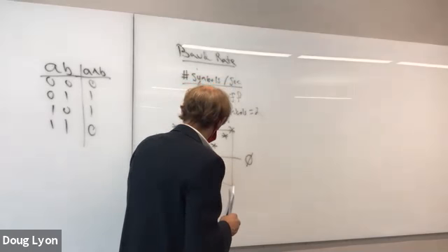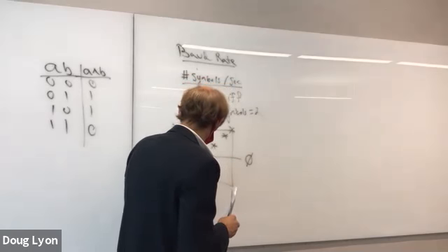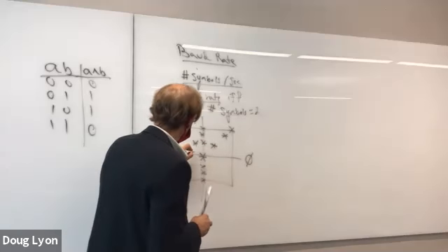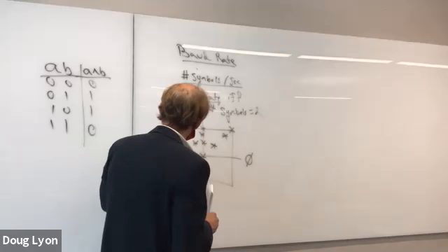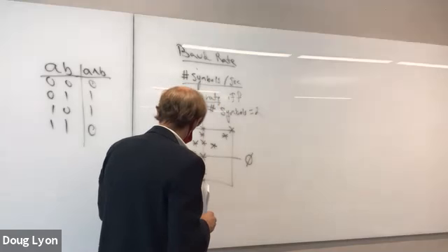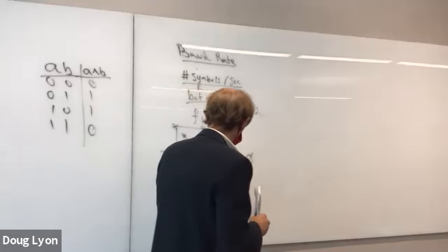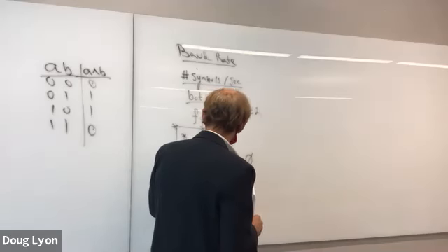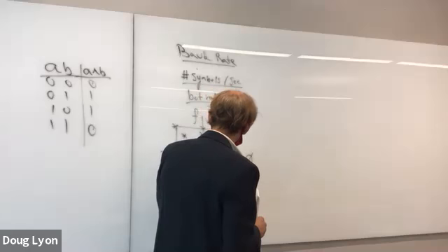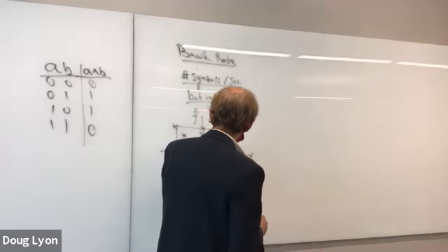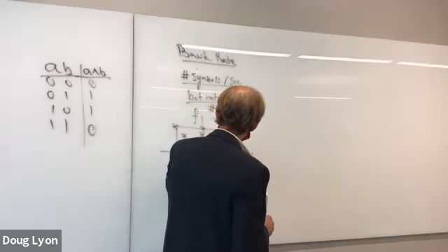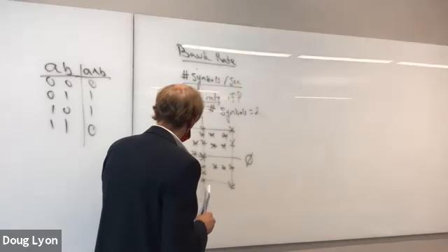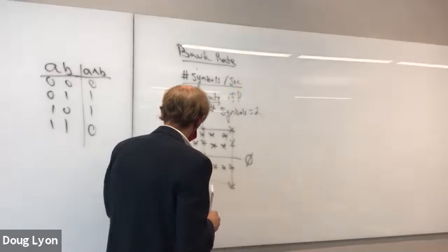And your maximum a posteriori receiver, also known as the MAP receiver, has a series of filters, which is able to determine when these symbols are being sent. And you can imagine it's just like a touch-tone phone where you send different numbers that have a dual-tone multiple frequency system associated with it. As many of these as you like, as many as can be efficiently discriminated.